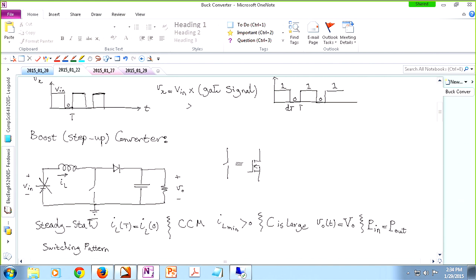So again, before, the converter was functioning, so there was a loop or conduction path for the inductor. You just turn it off. You have actually eliminated that, or you have physically disconnected your source from your converter. The inductor current has to flow through somewhere, and it just creates a huge spark and kills something basically.